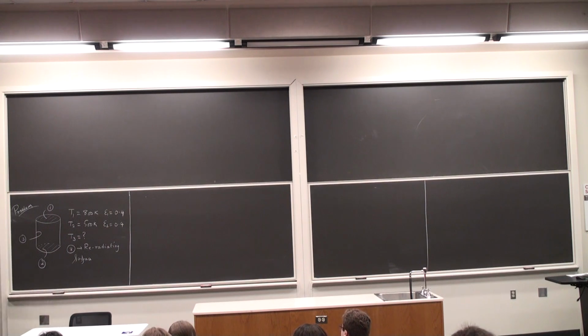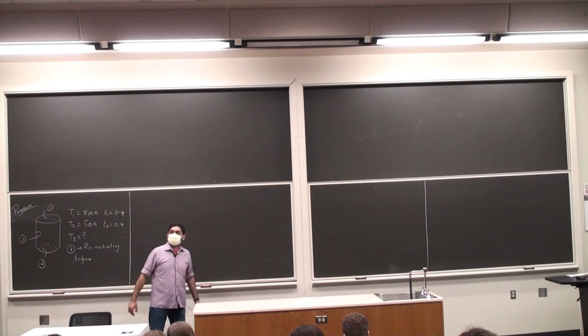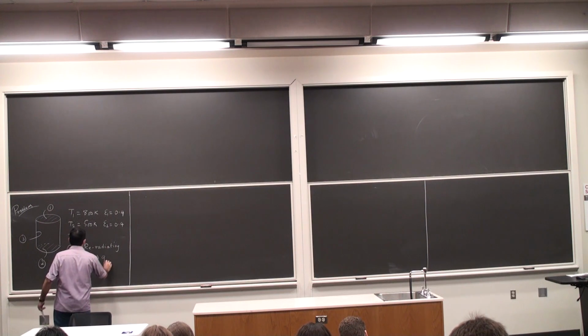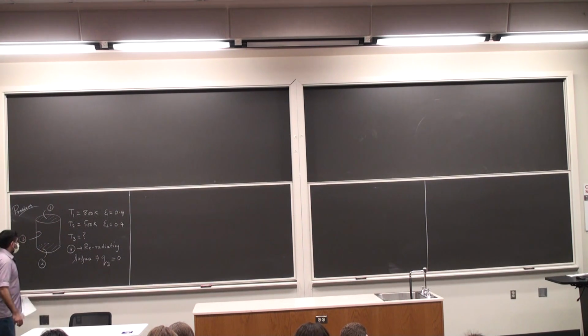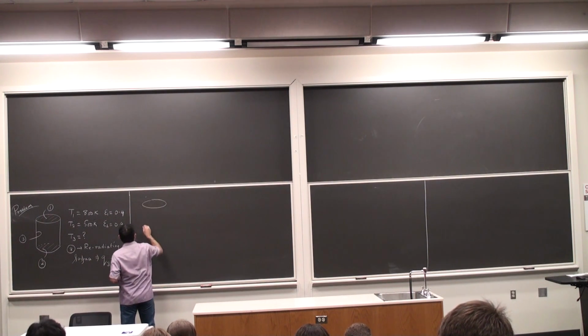Which essentially means that it's insulated, so there is no net heat flux coming out of surface 3. So this implies that for surface 3, Q3 is equal to 0. No heat flux coming out of surface 3. And similar to what we had for the last problem that we solved on Monday, I'm given the formulae for the view factors. It's a similar formula. Oh, it's the same thing actually.